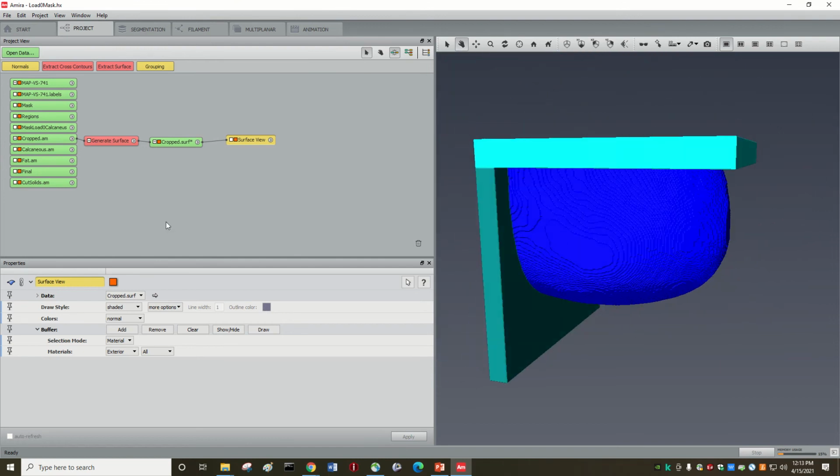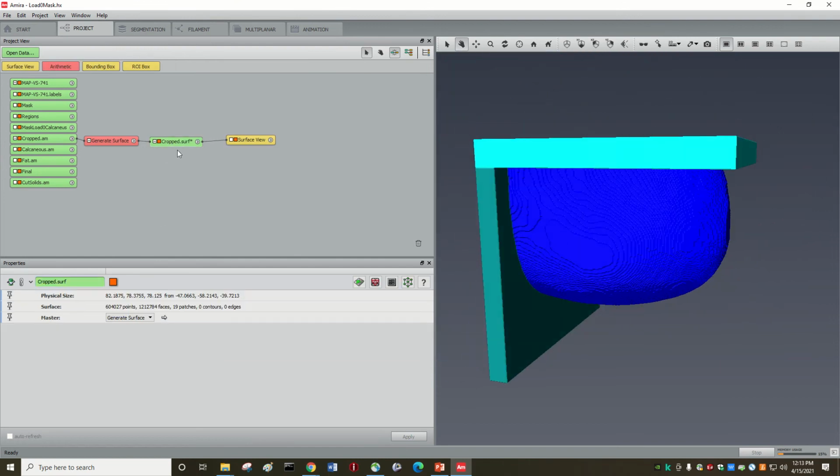So what we need to do is we can go on this surf, and now we have these two tools. One is surface editor, and the other one is simplification editor. So we will use both of them. So we can start with simplification editor. So here there is simplify. So we start with, well, 1,200,000 faces, basically.